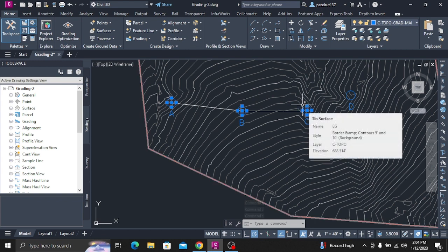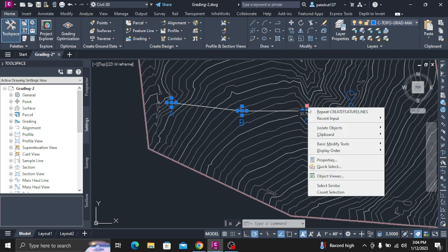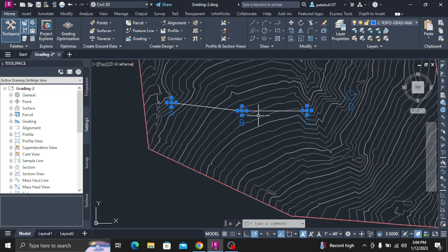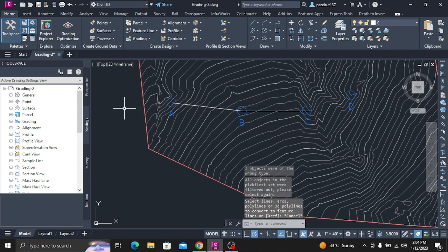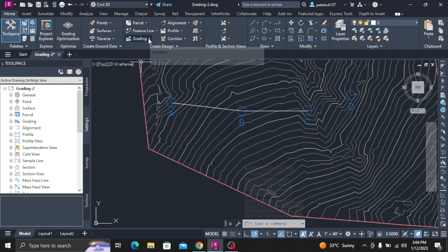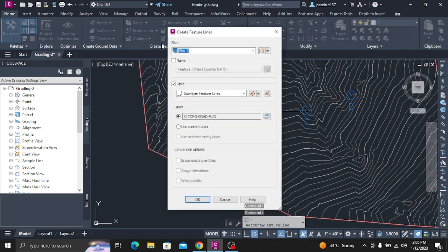Click the feature line that stretches from Circle C, D, E, to F. Click, and then click the feature line between circles A and B. The Grading Elevation Editor now displays the elevations along the feature line between circles A and B. Double-click the elevation value for the starting station, 0+00.00, and change it to 630.00 foot. This value puts it a few feet below the surface. Change the elevation of the end point to 690.00 foot.